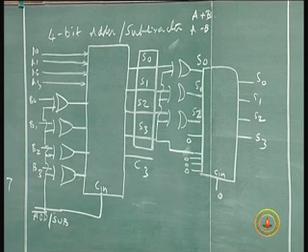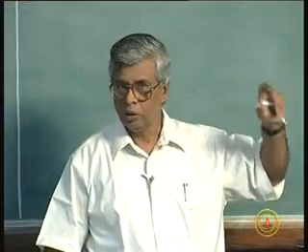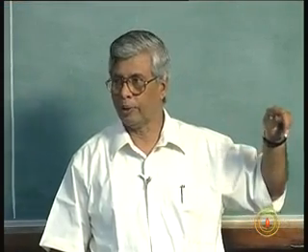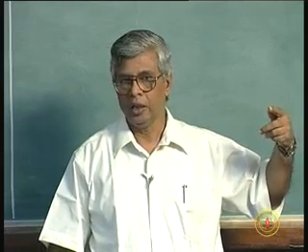We talked about subtraction, complementing numbers, 2's complement and 1's complement. We said how 2's complement addition is the same as subtraction. We also saw how a common hardware adder can be used for 2's complement addition as well as subtraction, by taking the 2's complement of the number to be subtracted.